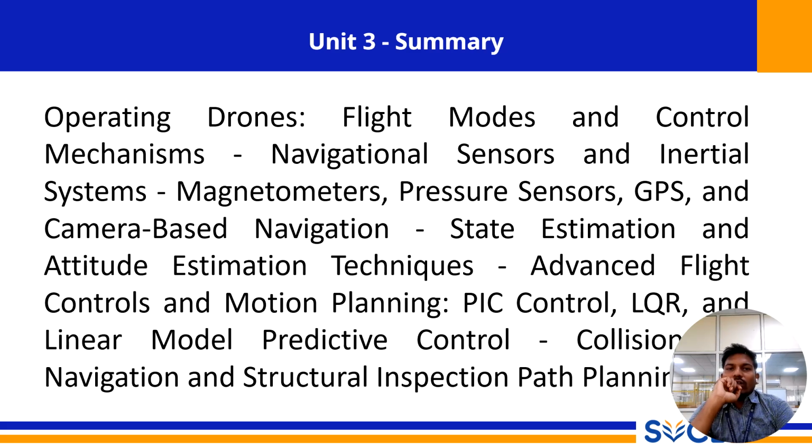It operates in a constant two-step cycle: a prediction step, where it uses a physical model to predict the drone's new state, and an update step, where it uses sensor measurements to correct its prediction.